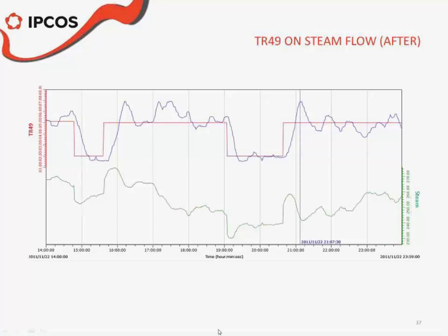This is the result. You can now see how, if you make a set point change, the process actually responds and reaches the new set point, both down and up, and it keeps at set point all the time. So it's not like before, in which you saw the ratio just going up and down, and having no real effect on the temperature.